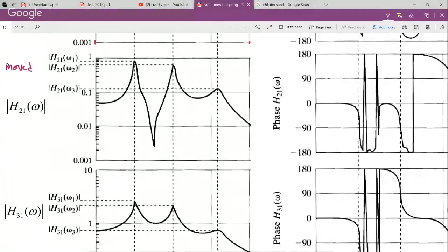We hit the hammer location, there's a response, and we still get a magnitude for the frequency response. All we did is move the accelerometer. We still get the same three natural frequencies. It may not look like it, but you should get the same values within estimate error. You should get the same damping ratios. But, like you said, the magnitude is going to change. Why?